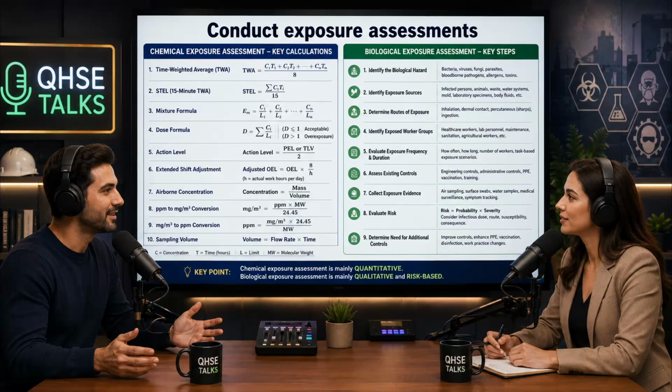Let's bypass the heavy calculator work and look at the practical reality of the source example. Sure. Under OSHA regulations, an environment at 90 dBA allows for 8 hours of exposure. That's the baseline PEL. But if that noise level goes up to 95 dBA, an increase of just 5 decibels, the allowable safe time doesn't drop by a few minutes. No, it drops all the way to 4 hours. You have cut their safe working time in half. And if it goes up to 100 dBA, the safe time drops to 2 hours.